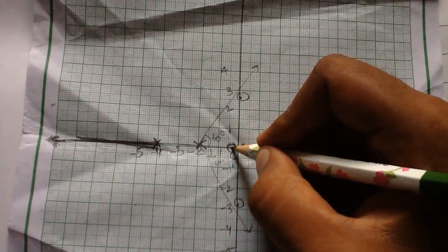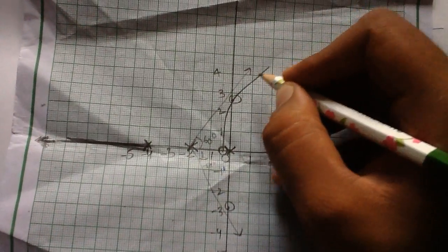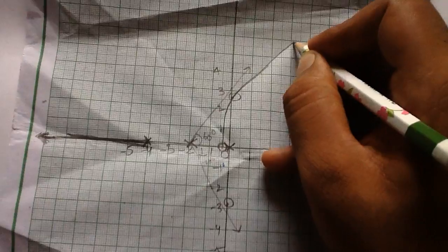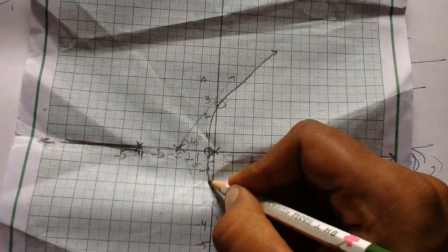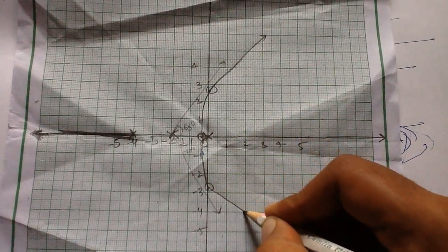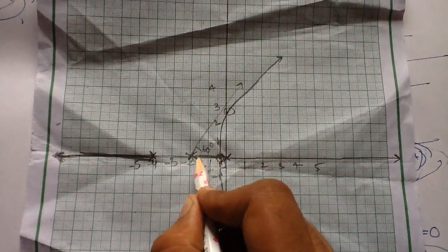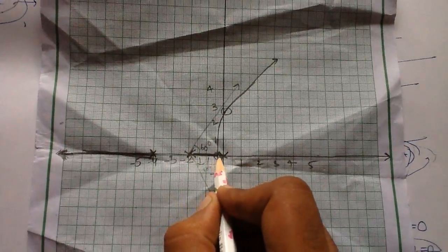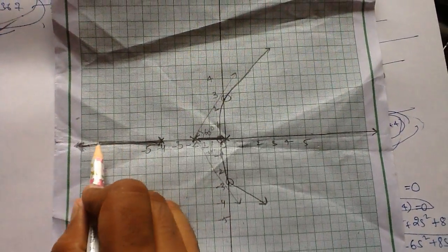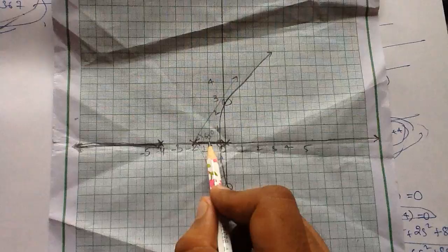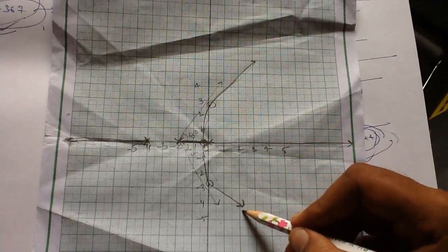So starting from the breakaway point, draw lines along the asymptotes such that they meet the imaginary axis at the required point, and it goes to infinity. And the same thing with the other half, and it goes to infinity. And minus 2 and 0, this is also a part of the root locus. So now tell me, what is the root locus in this whole picture? 0 to minus 2 is part of the root locus. This line is part of the root locus, and this line is part of the root locus.